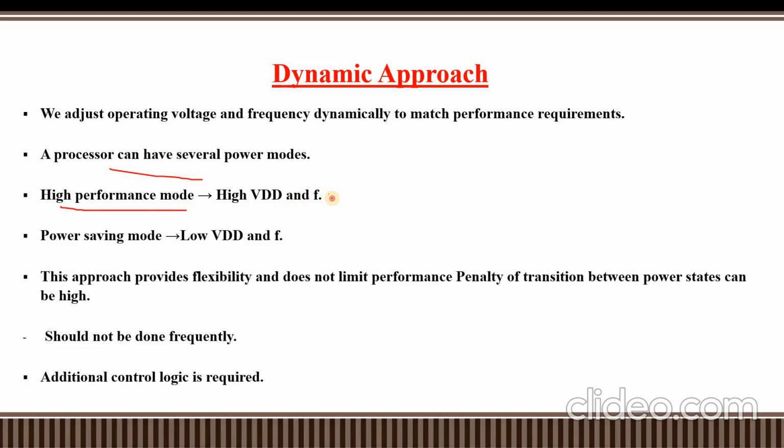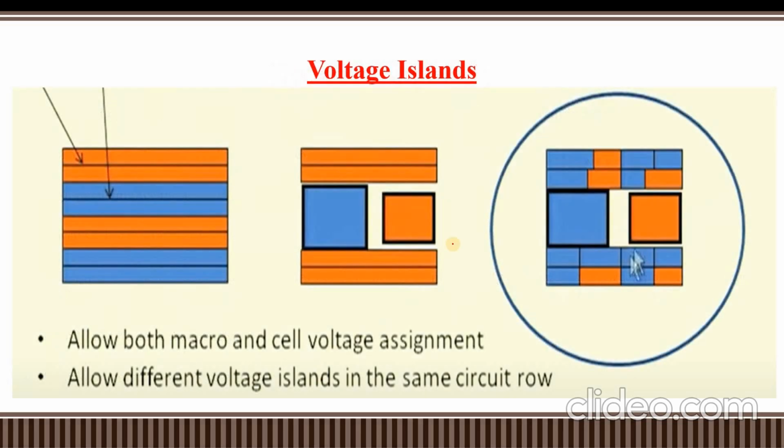Okay, it has high VDD and high frequency, and power saving mode, another mode, that is low VDD and low frequency. This approach provides flexibility and does not limit performance, but the penalty of transition between power states can be high. So the dynamic approach can require additional logic. So let us see these voltage islands, this orange color and blue color.